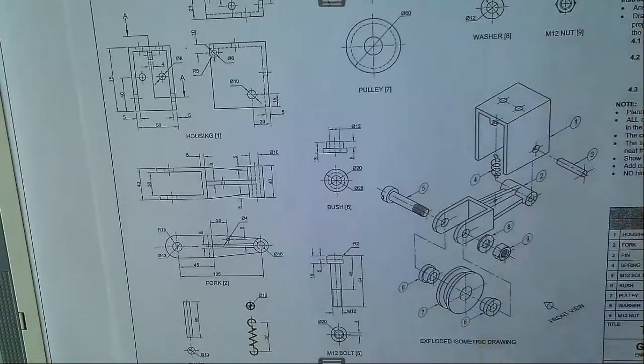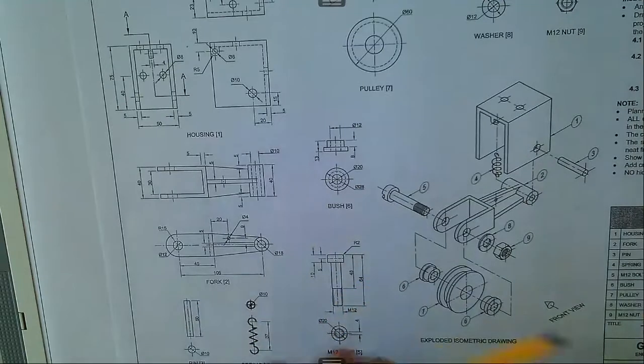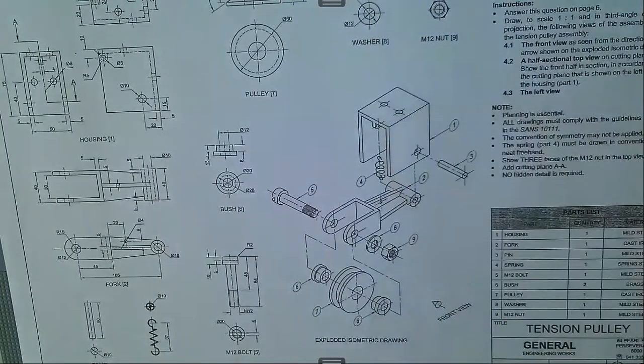So that is the exploded view. When you are looking from this side, you are looking at the front view. When you are looking from that side, you will check, we are looking at the left view. Then, of course, if you are looking from this side, you are looking at the top view. Remember in paper 2, we basically make use of third angle orthographic projection. So if there is a top view, it has to be drawn at the top and in line with the front view. And if there is a left view, it has to be seen from the left and in line with the front view as well. So it will be directly in line with the front view. The top view is directly on top of the front view.